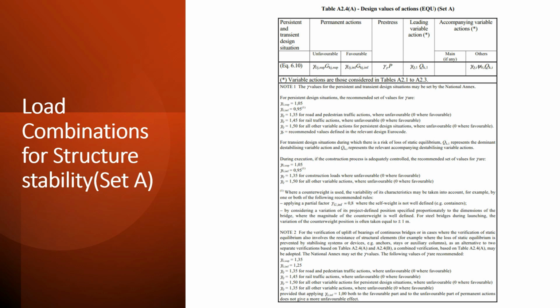So if you have not watched that video, please watch it, then only you can understand this load combination system. If you have three or four variable loads, every time you have to consider one load as the leading variable, and the other loads are associated variable loads with the leading variable load. That way you can make three, four or five combinations through permutation and combination.